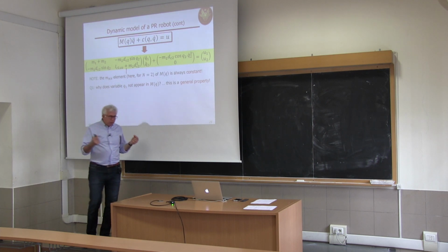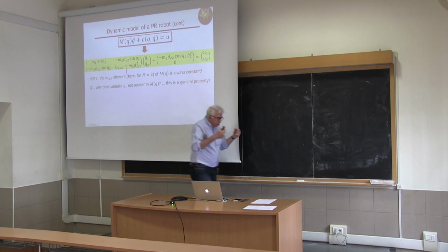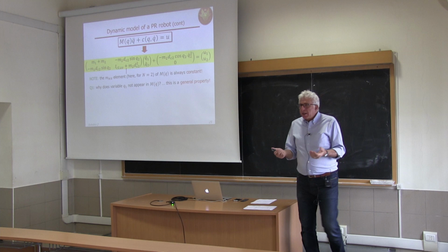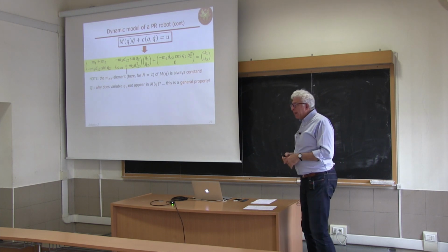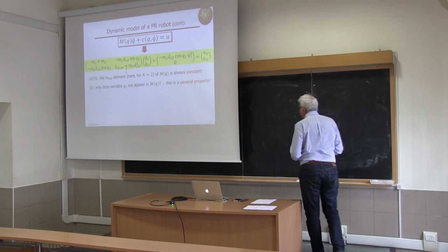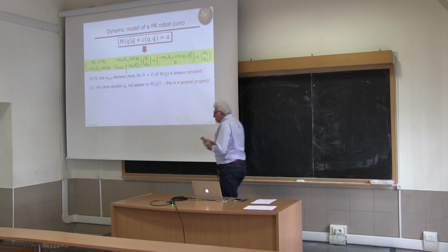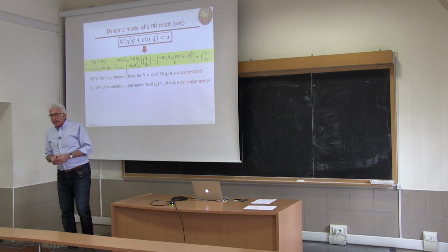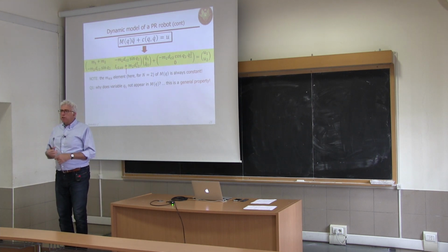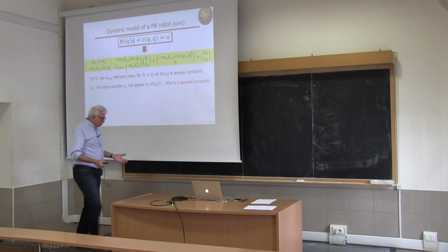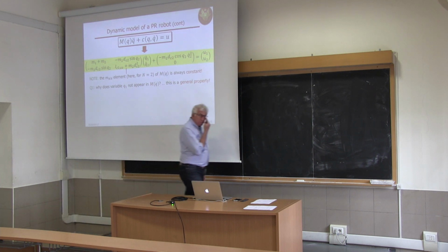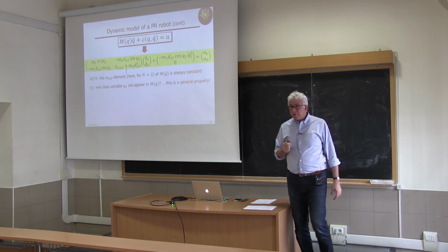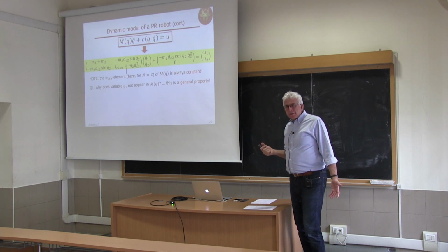If you reason, and in particular, if you consider that in general we introduce the coordinates, if possible, using the Denavit-Hartenberg notation, you know what the q1 variable is in that notation: if the joint is revolute, it's related to the θ1 variable in the Denavit-Hartenberg notation, and if the first joint is prismatic, to the d1 variable. Those variables are defined with respect to a frame, the zero frame, which is somewhat arbitrary.